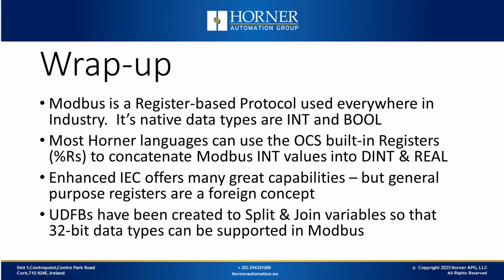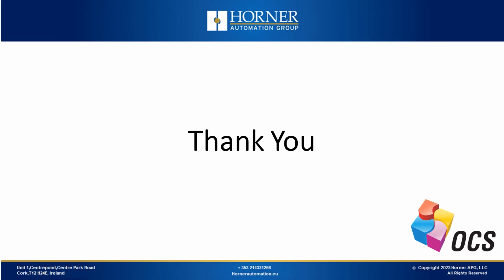In conclusion, Modbus is widely used in industry and supports 16-bit integers and 1-bit booleans as its native data types. However, there's often a need to transmit other data types like double integers or floating points over this protocol. While traditional Horner languages can easily concatenate integer values into 32-bit data types using built-in %AI memory, Enhanced IEC lacks this feature. But we have simplified the process by creating user-defined function blocks for easy splitting and joining of data types. That concludes our webinar for today.